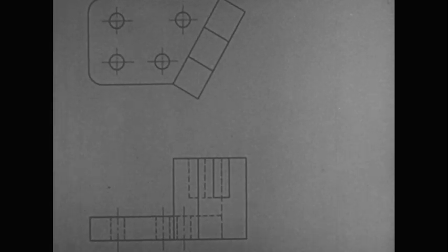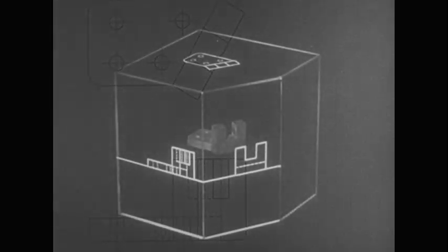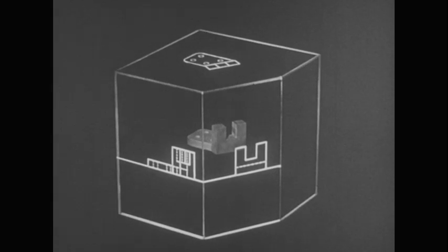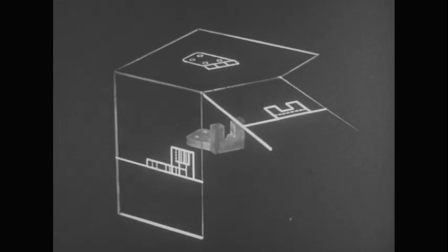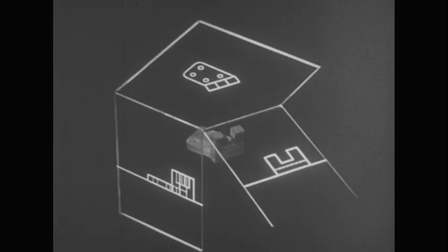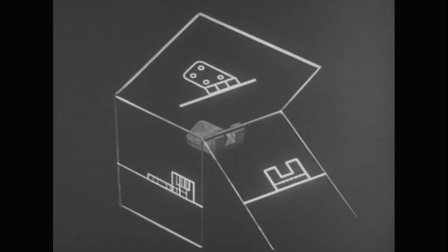In making the drawing, first construct the principal views as far as necessary. Then think of the relationship of the auxiliary plane to the principal planes. Imagine reference lines on the view which shows the slanting face foreshortened and on the auxiliary view. Then think of the views in one plane. The auxiliary reference line is parallel to the edge view of the slanting surface.